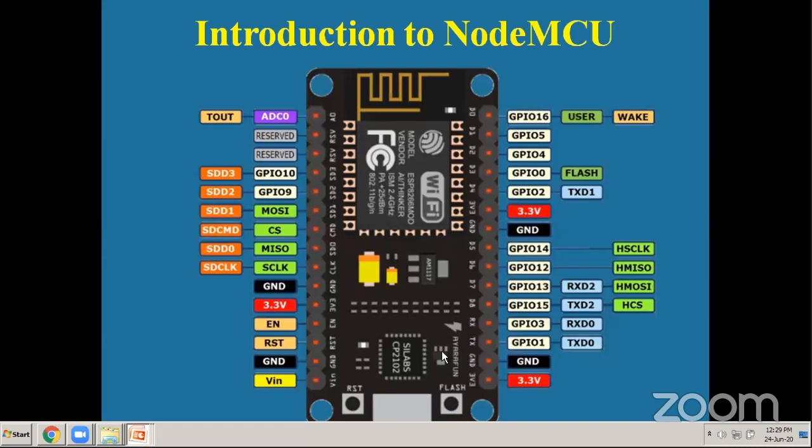Okay, so we have explained to you what a microcontroller is. We showed you how to write the code and how to upload it to the Arduino Uno. We connected an LED. If you had connected a buzzer instead of the LED, you would have seen it make sound for 1 second, then be off the next second. Then again it makes sound for 1 second, and so on. That continues in a loop forever, as long as you keep the Arduino on.